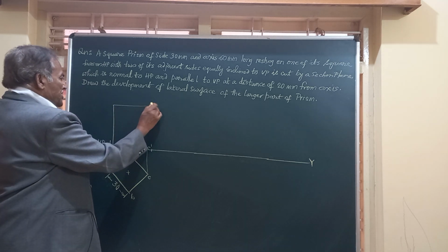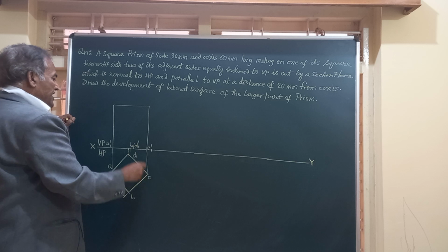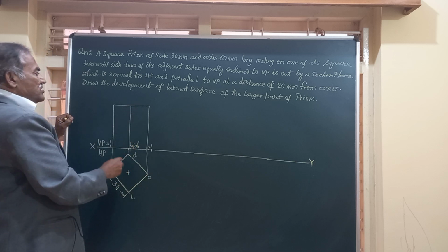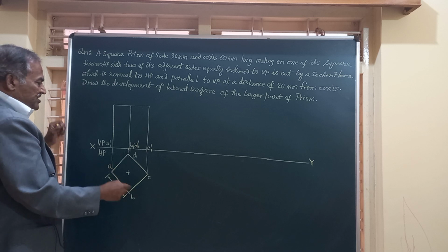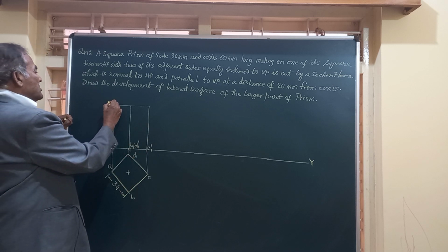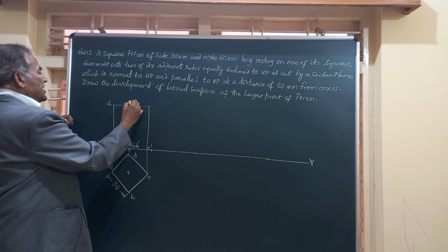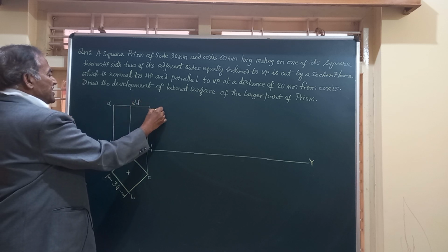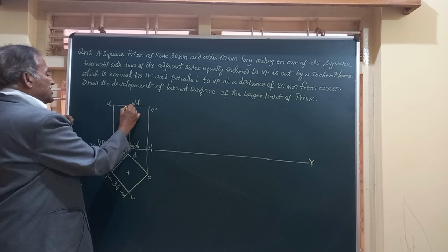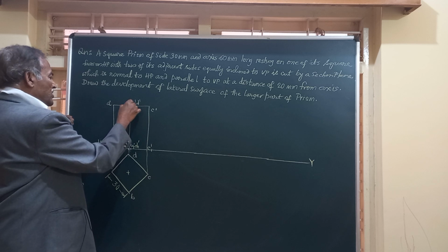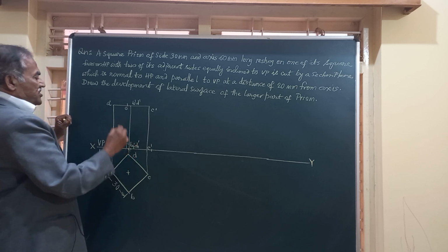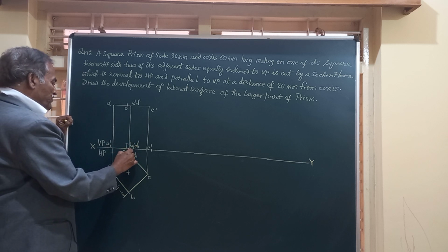The front view is going to be a rectangle like this, and in the center you have got a line, that is the one for this A. And here friends, we can mark this as A dash, B dash, D dash, this is C dash, this point is O1 dash, the axis is perpendicular to HP.